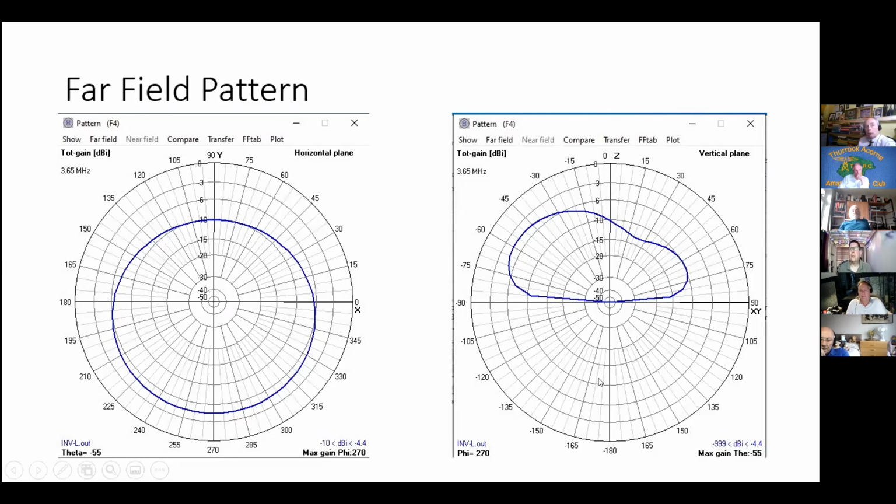And my experience with these antennas, and I also actually had an extra piece of wire that I could use to extend it to top band. And the greatest distance I've ever got on top band, which is Cologne in Germany, was using the 160 meter version of this. It works well for ground wave. It works very well for very long distance sky wave.